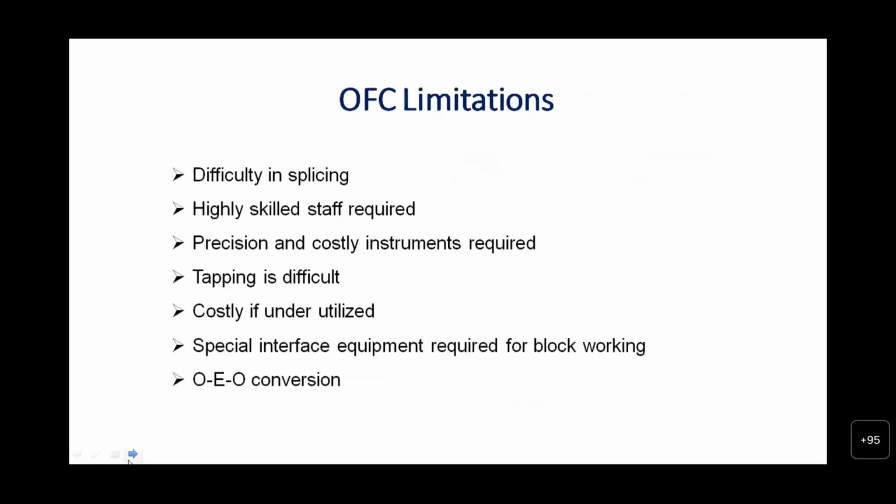However, there are some limitations in OFC. There is difficulty in splicing. Now even this, many of the technicians and ESMs have got experience in doing themselves. Hands-on experience is already had by many of the technicians. And it requires highly skilled staff, precision, and costly instruments to test it. Tapping is difficult.